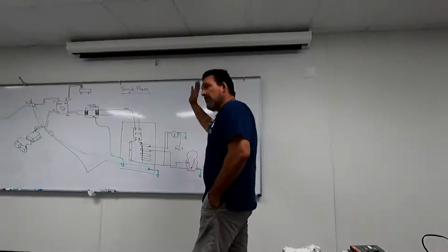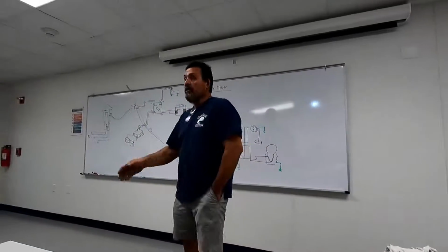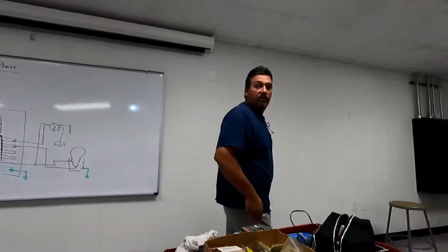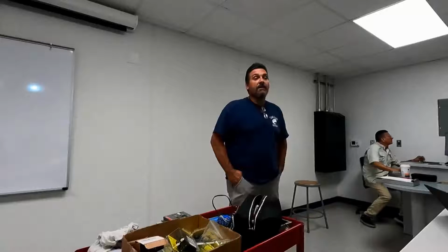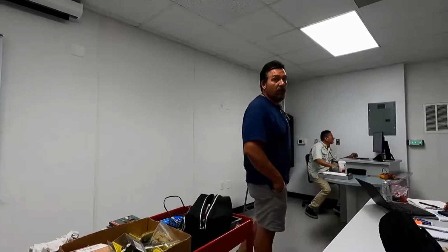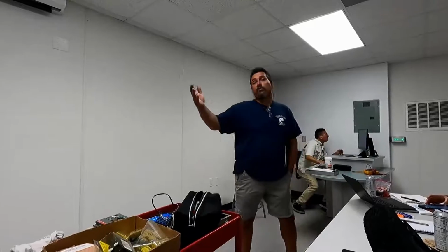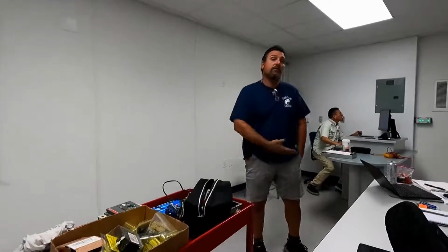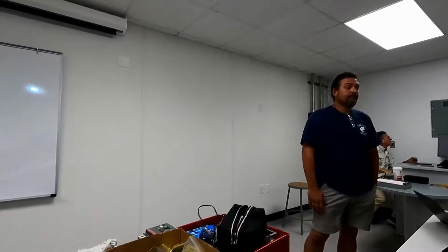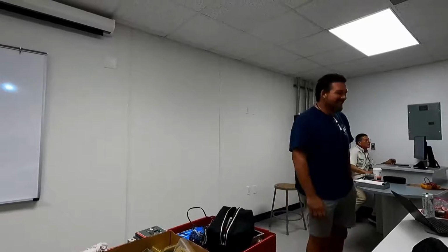If it takes it out, just take out the bus bar and that's it. Because the bus bars have a certain amount of amperage you're allowed to use. So don't just buy any bus bar and assume it's going to work for your application. You have to make sure it can withstand the amperage. You have some bus bars at 250 amps, 500 amps, and you have some that are 20 amps, 40 amps. Everybody just looks at it as a bus bar. Oh, it's a bus bar.